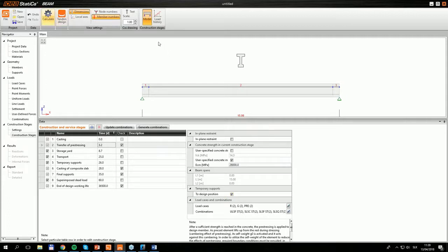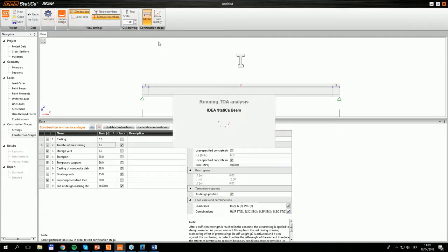Okay, and once we calculate the whole model, we are able to input the data for the stability of the beams, and it runs according to chapter 5.9 in Eurocode 2-1, which basically covers two different situations, where one is persistent and the second one is transient.